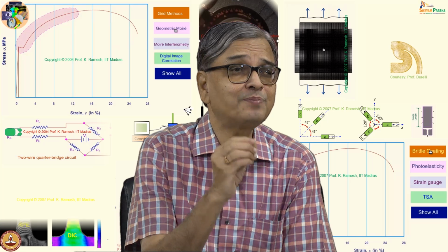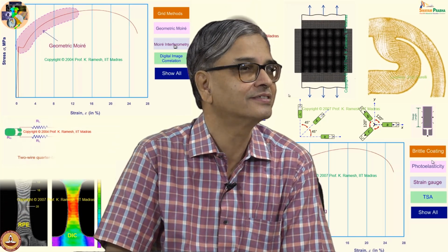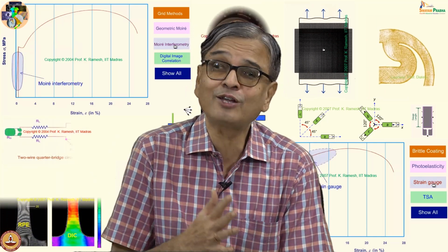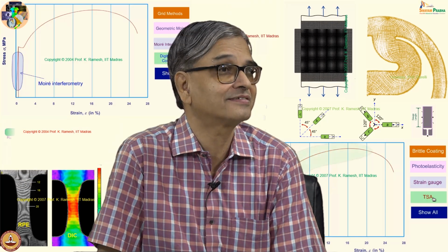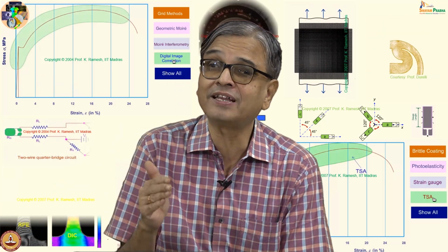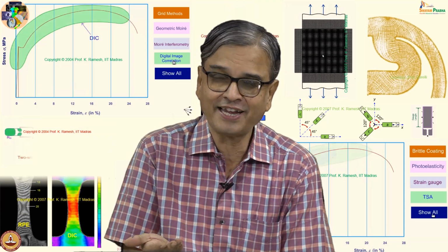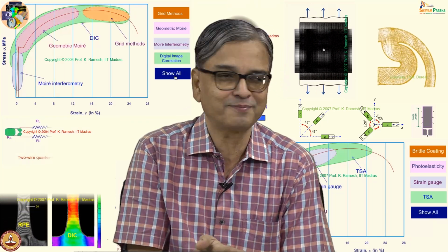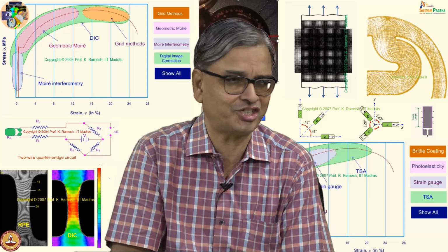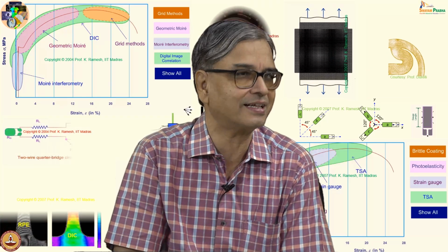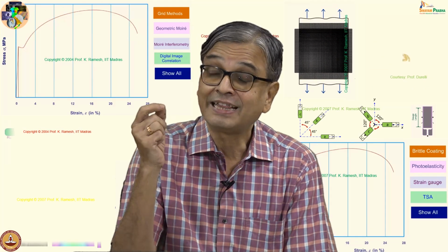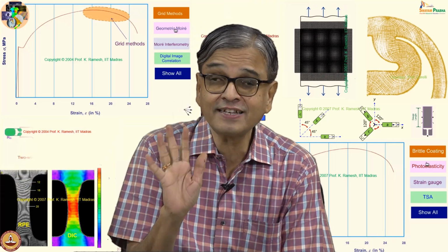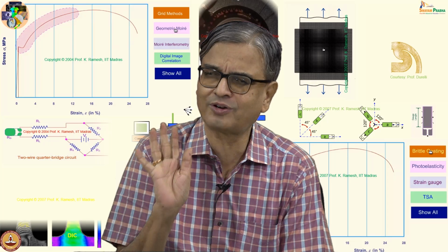Now I have a very small tiny strain gauge. I am going to pass current through this. This also acts like a micro heater, I squared R loss is there. Because I am going to measure 10 power minus 6, you can't feel the heat. In a domestic heater, it is 1000 watts. This will be very small wattage, okay, 0.04, 0.06 or something like that. But that heat generation also affects your electrical response. So you have to be very sensitive that you are measuring extremely small quantity.